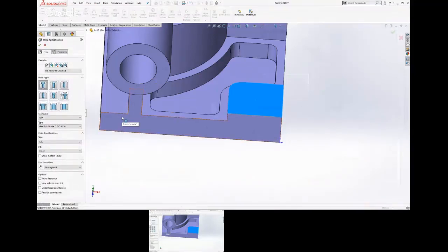The variables are in our document. What it calls out is basically we give you everything starting from the top to the bottom. So this is an ANSI metric counterbore. So counterbore is selected. Obviously the standard I need to change to ANSI. So it's ANSI metric. And then it's a hex bolt. And it is an ANSI B18.2.3.5. So you see it's there. The size is M8.